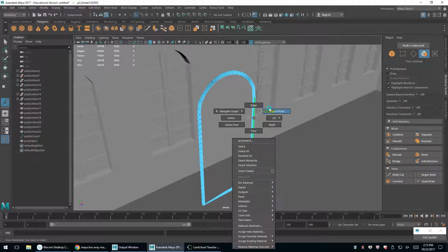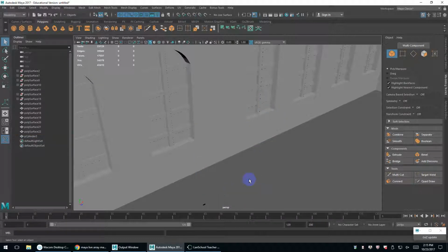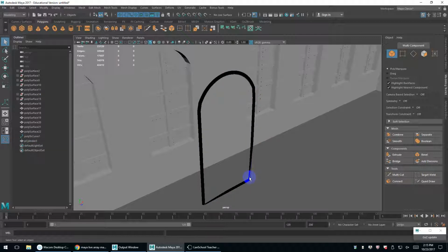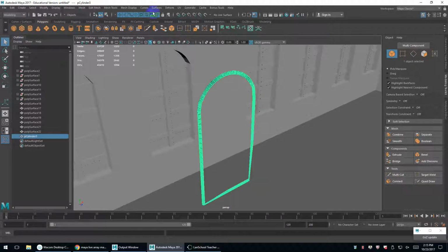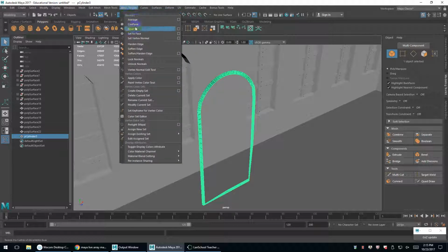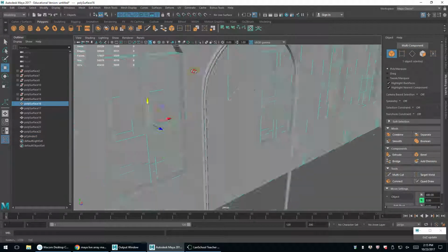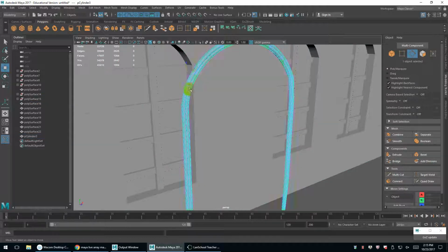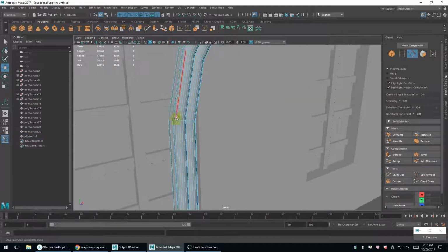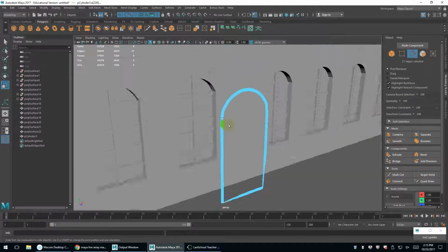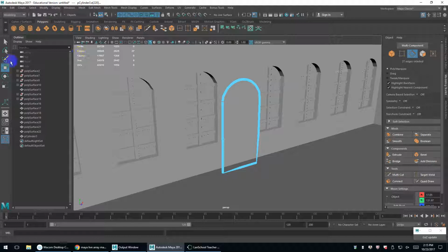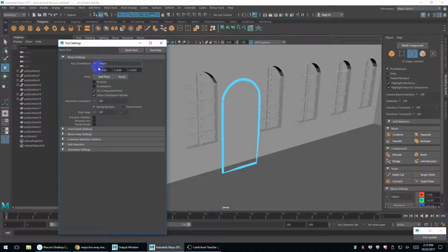There is a little bit of touch-up often with this stuff. It does get a little messy, so I'll go to that spline. Oops, actually I should grab this object, delete its history because it's still connected to the NURBS curve. Delete the curve, grab the mesh, reverse the mesh. So now we've got a bit of trim, right? Maya is still not kind of great at some of this stuff, so I usually find I have to tweak some of the corners and the turns in this stuff. So I'm going to, yeah, let's grab this thing. Let's just reset the tool here.